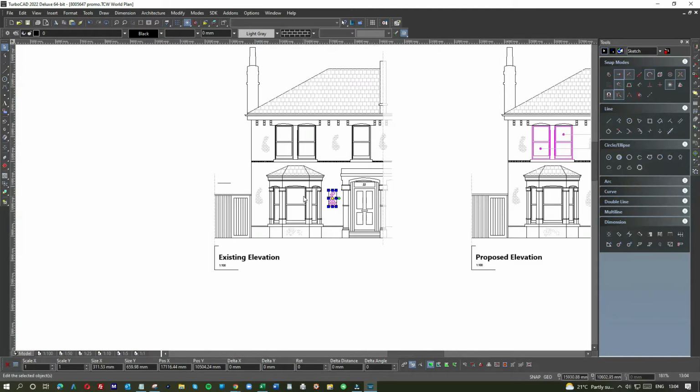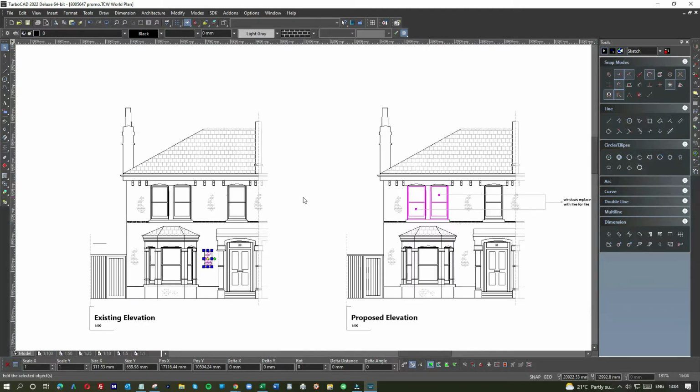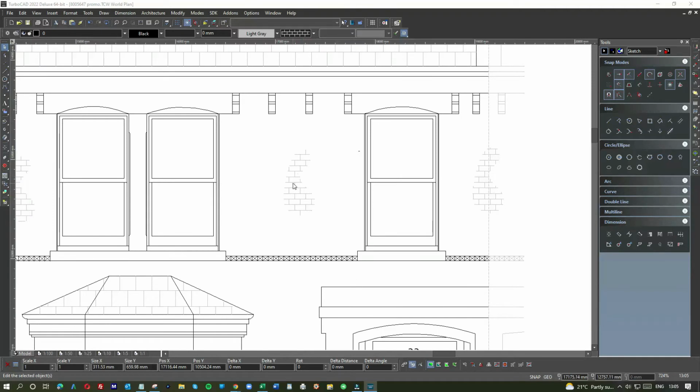So this was done, by the way, from photographs. I didn't visit the site. I went on Google and had a look at Street Map, and there was a big tree and loads of creeper all over the front of the house, but that was easy enough to solve because it's a street of the same houses. So I just went 2 doors down, picked the cleanest, best looking photo I could, and made sure then that it matched up, and then went ahead, and because we had brickwork we were able to scale from the photo. Each brick, we know what the measurements are with or without the mortar, so we scaled it from the brickwork.